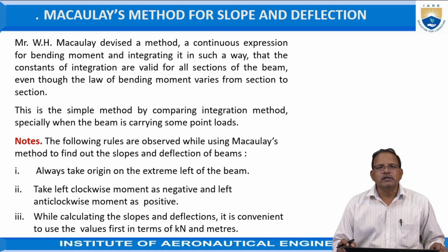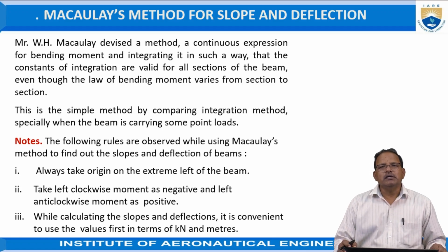When comparing this method with the integration method, this is one of the simplest methods. It is applicable not only for a beam subjected to a load acting at one point, it is also applicable for beams which are subjected to a number of point loads, or a combination of a uniformly distributed load as well as point loads on a simply supported beam. So the following rules are observed while using Macaulay's method for finding the slopes as well as the deflection of the beams.